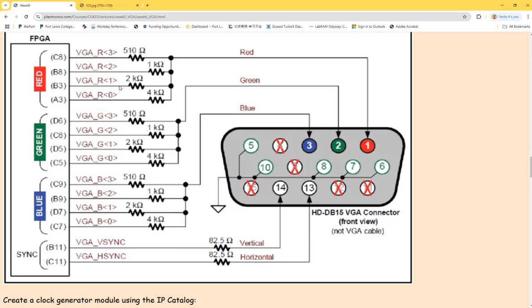Then why is this MSB contributing a higher voltage to this guy, with higher weight? Because of the lower resistance. Why? Then remember, how do we do superposition? Alright, think about that.